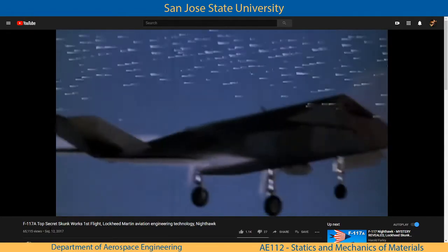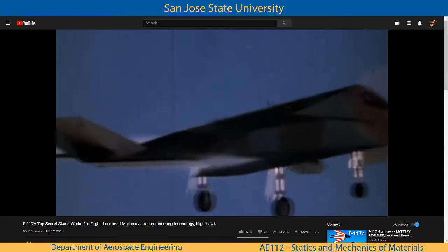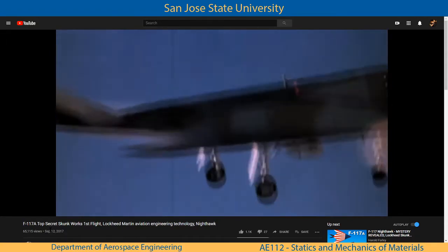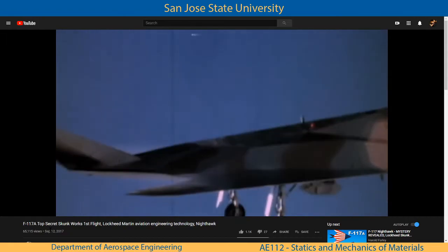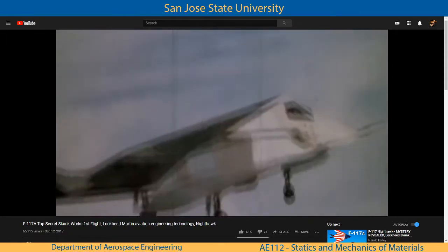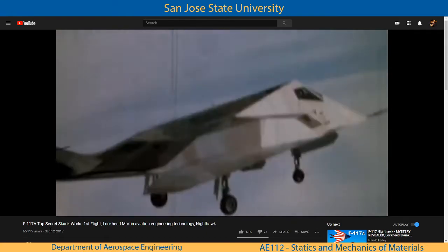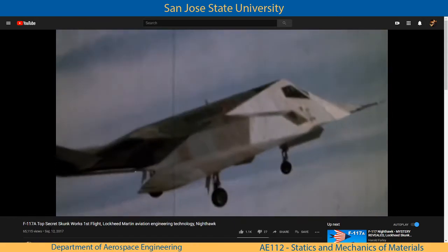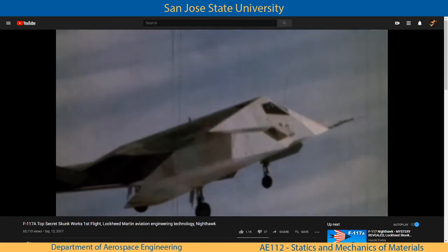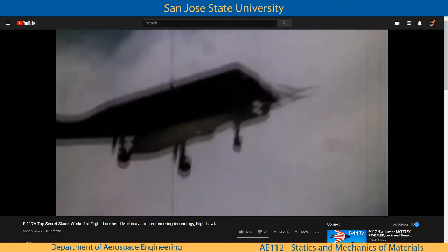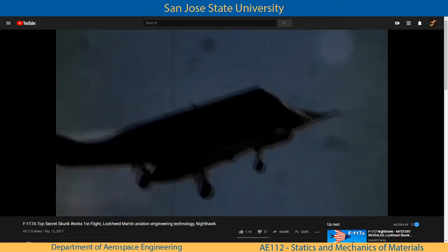We had overheat in the tailpipes because the tailpipes were rectangular, and in the corners heat builds up, and they were reaching limited temperatures. And we also had the canopy unlock light that came on, and that was of concern because if the canopy had come off, you get a face full of wind, and it was marginal about whether you could land the airplane or not.